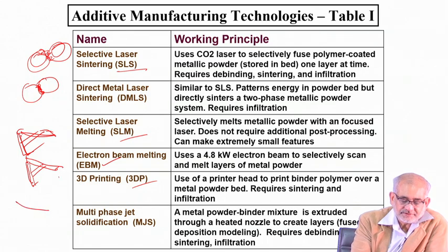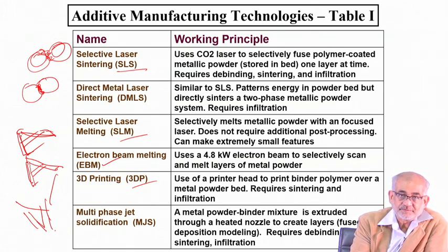Now, usually the powder feed and the laser can be different, coming from different directions, but in reality it's also possible that you have a laser beam coming through a particular nozzle, and you have a concentric feeder or hopper around it which can feed one single or multiple powders.